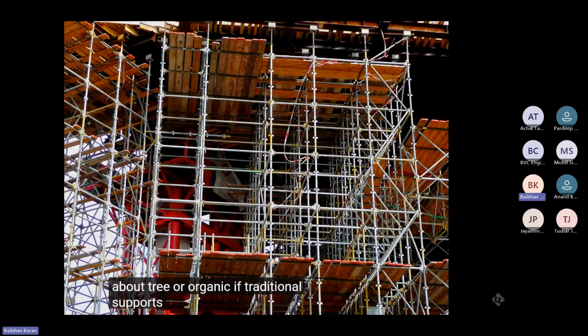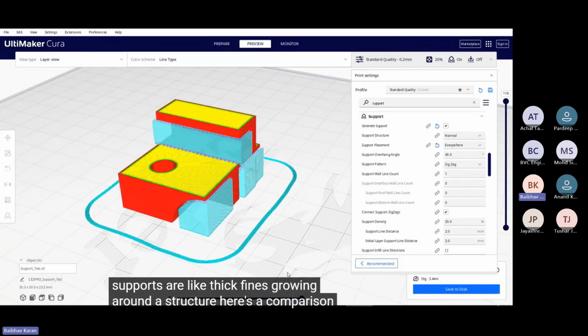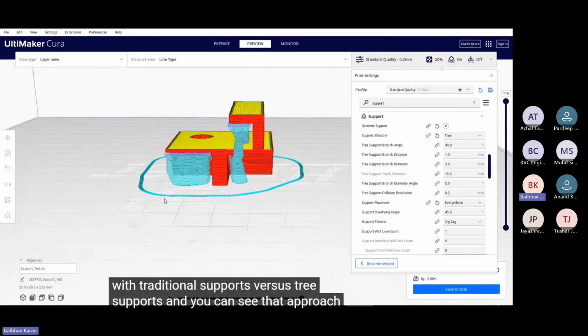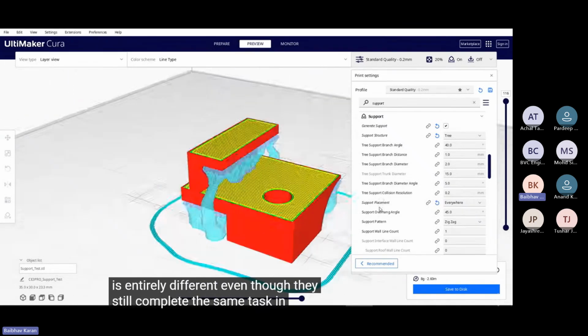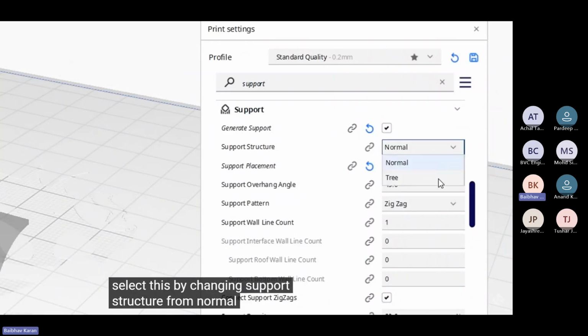If traditional supports are like scaffolding on a building site, then organic or tree supports are like thick vines growing around a structure. Here's a comparison with traditional supports versus tree supports, and you can see their approach is entirely different even though they still complete the same task. In Cura, we select this by changing support structure from normal to tree.